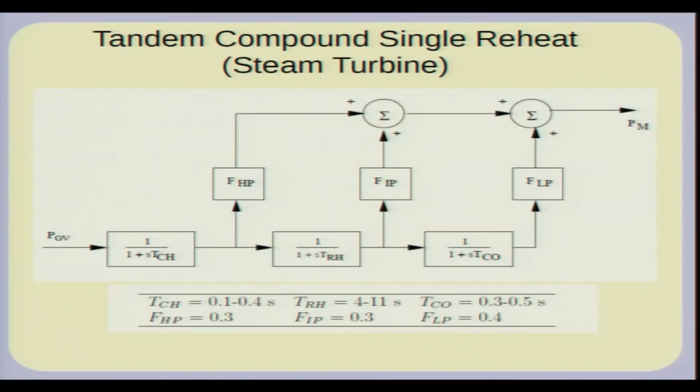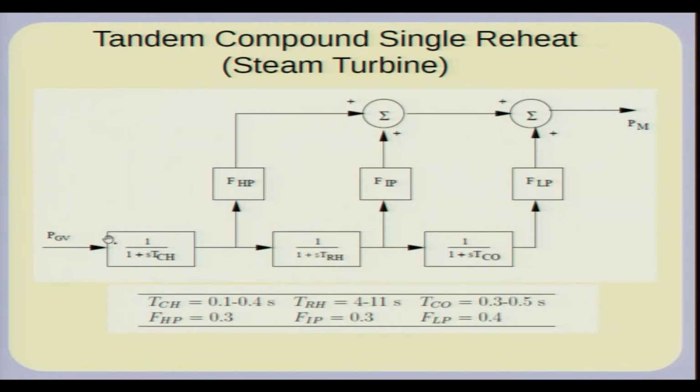So, the idea is the same as in an excitation system. You have got a closed loop excitation system, a closed loop speed governing system. Remember that the turbine itself is not instantaneous. If you for example change the valve position, even changing a valve position requires a bit of dynamics of the servo mechanism which actually changes the valve position. The turbine itself, the output does not immediately change. In fact, for example, if the gate position is changed, this is a kind of a per unit diagram.